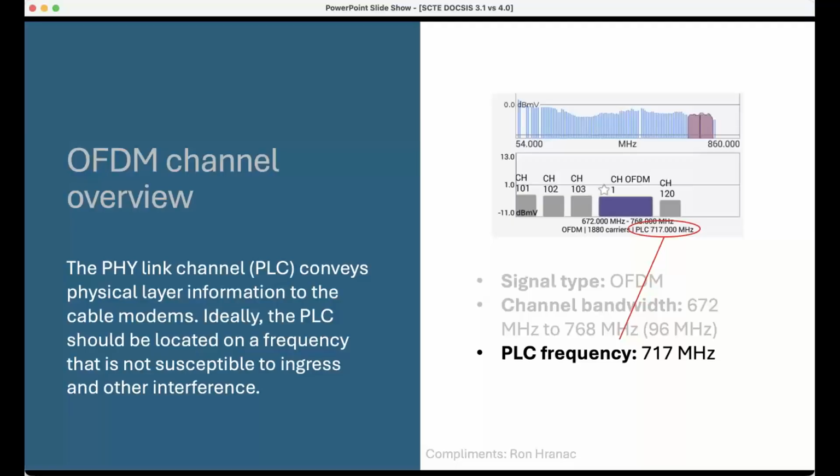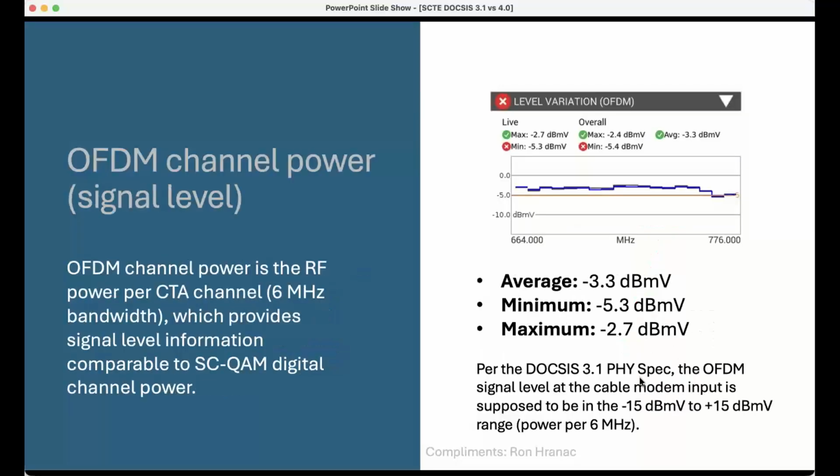If you did not have that exclusion band in there, maybe the modem would only be able to run at 256 QAM, which would give you a very different speed than if you put that exclusion band in, and now the modem's able to run at 4096 QAM. You'd get a very different speed there. So I couldn't tell you the exact speed without taking you to that calculator. So it depends, but I hope I partially answered your question with explaining the exclusion band and why we use it.